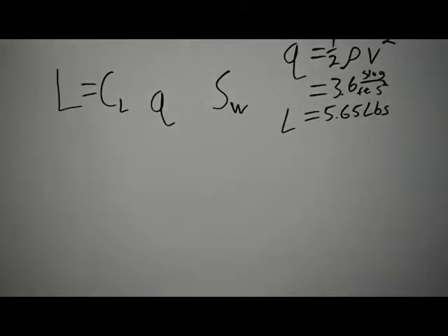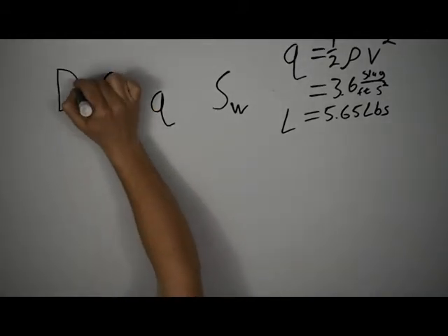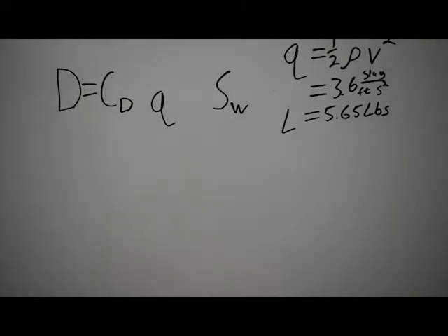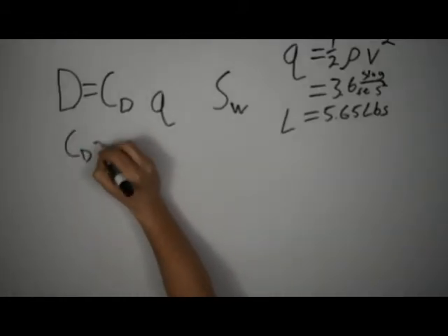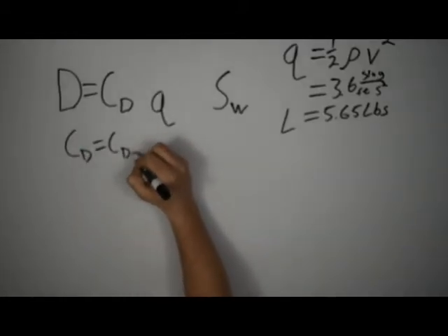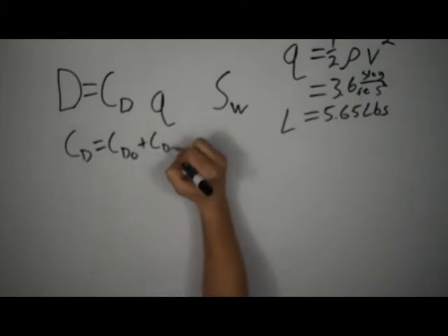And the drag equation is a little different than the lift equation, and I'm going to blow your mind right here. I know, so much different, right? So we do have one little complication with this, in that our coefficient of drag that's listed here isn't just the coefficient of drag that we pulled from Airfoil Tools. It's that plus an additional coefficient of drag that's based on the coefficient of lift, called induced drag.